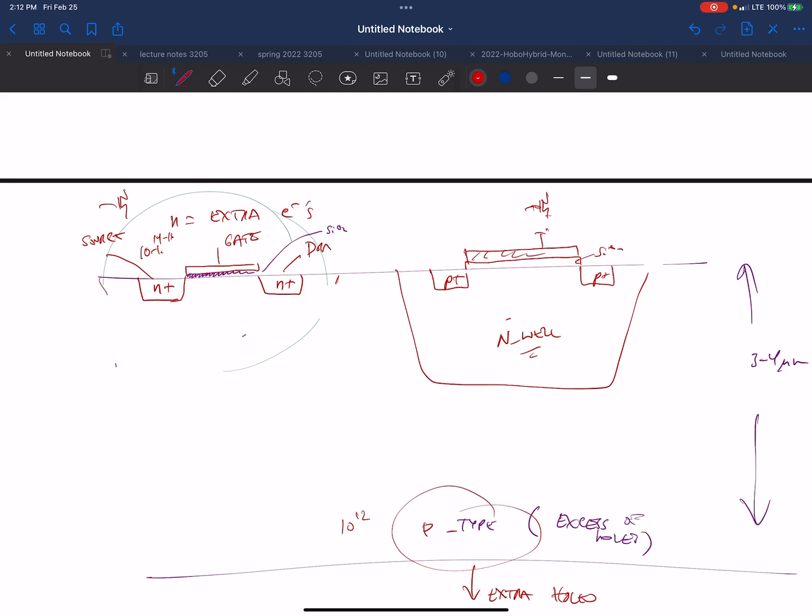The thickness of that gate, imagine you're talking about 20 atoms of silicon dioxide or 30 atoms, but we're not talking about 30,000 atoms. So the oxide that you build for your gate has to be incredibly pure. And imagine again, with 20 billion transistors, if one of them has a short on the gate, your device is toast.